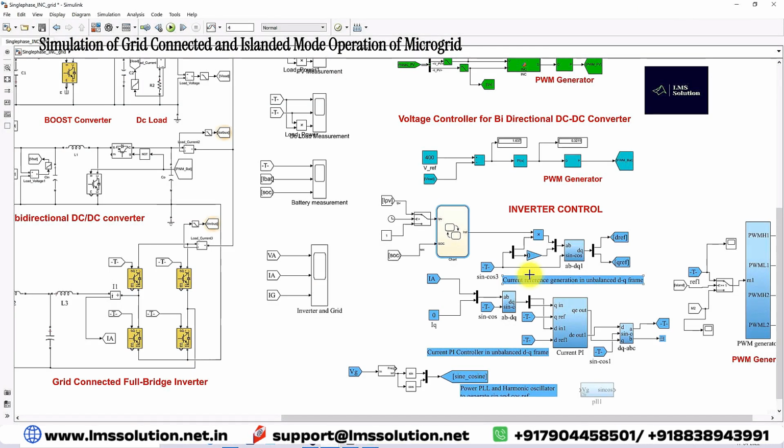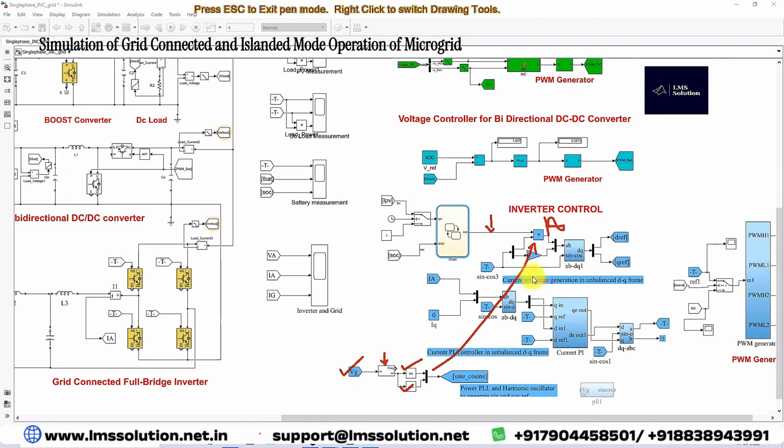So here also we convert the reference current, which is in magnitude, so that it should be changed to sinusoidal. In order to change it to sinusoidal, we are using a PLL here. We measure the grid voltage, which is converted into omega t by using the PLL, and then we generate the sine cosine waveform, which we multiply with the reference to convert it into sinusoidal form.